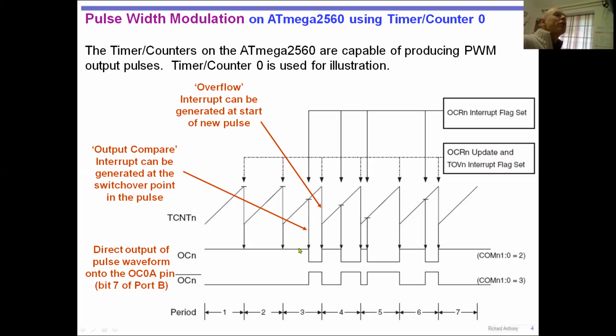There are two reasons that could occur, by the way. One is the actual timer mode. When we program the timer, you will hopefully remember from the 5th or 6th lecture, we set the mode of it, and it might not be in PWM mode. It might be being used for something else. The other possibility, although it's hard to show on a diagram like this, is that the output compare value was set to 0.